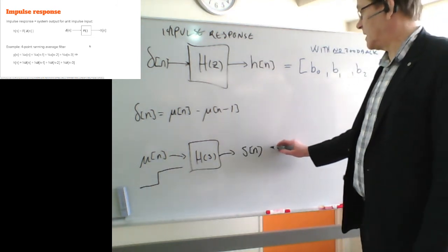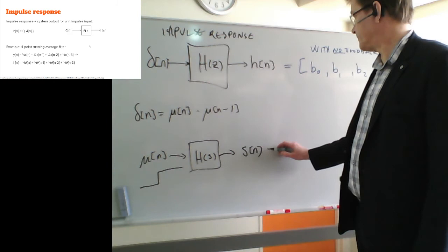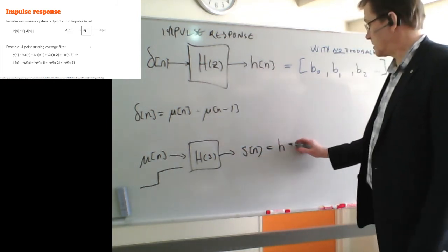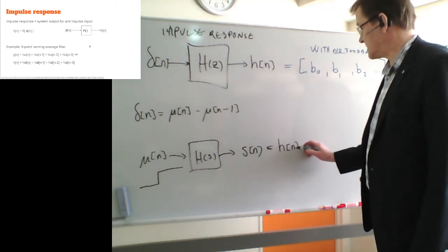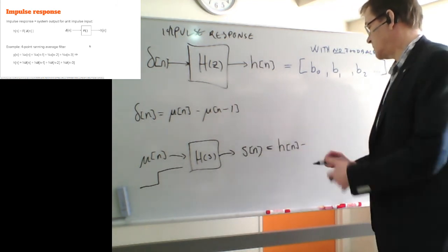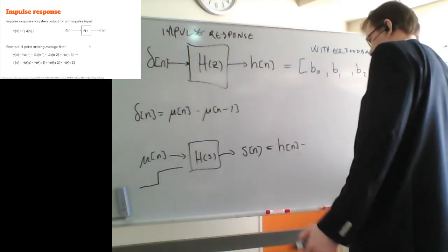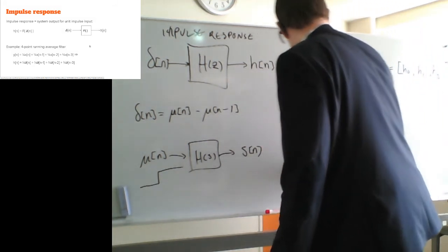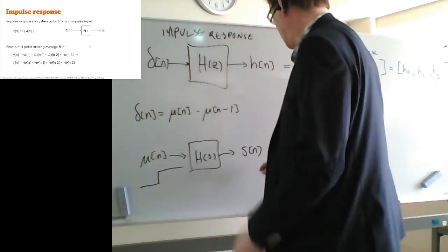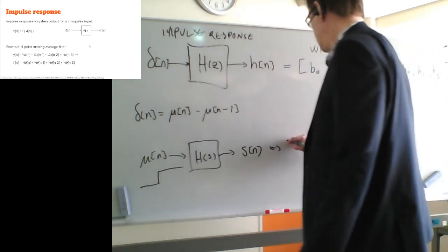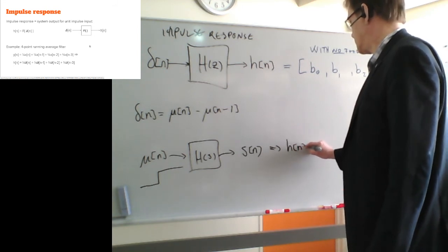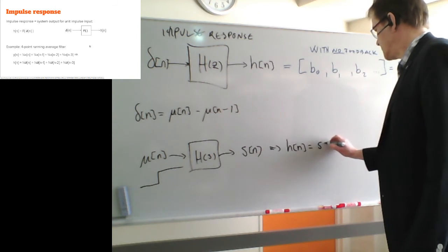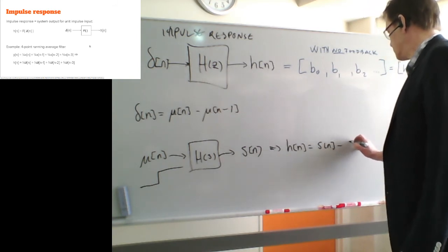And if the system is linear, then this is actually the same as, oh, sorry, that way. So you can calculate the impulse response from the step response.